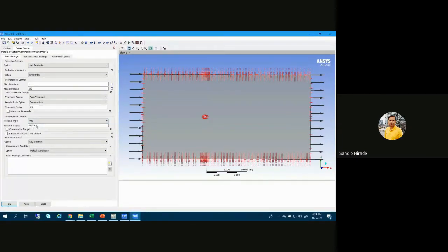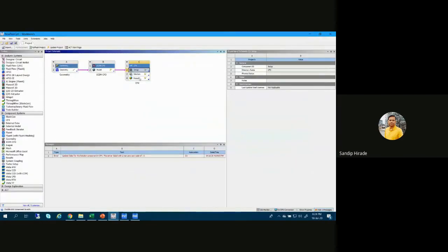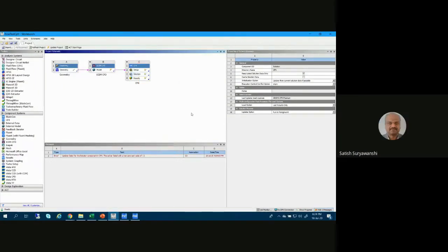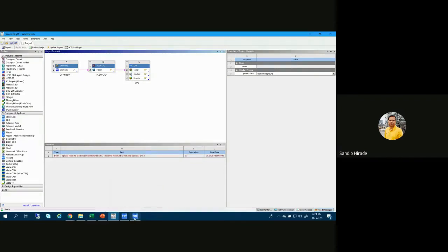This is the first one. The second, you can put monitor points in your simulation, and you can check whether the monitor point shows a steady variable in your solution. And third, even if you have monitor points, if the simulation is unsteady, you will not get convergence. Then you need to see whether your physics is correctly modeled or not. So you will have variation. I can display the monitor, so let me just open the solver.